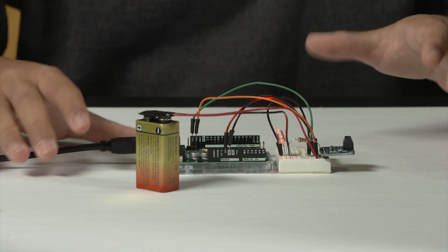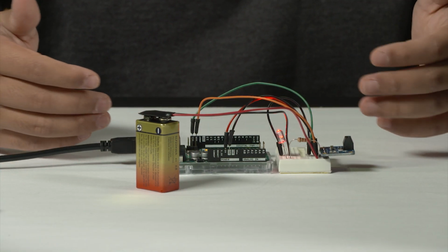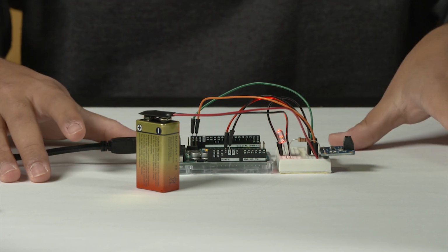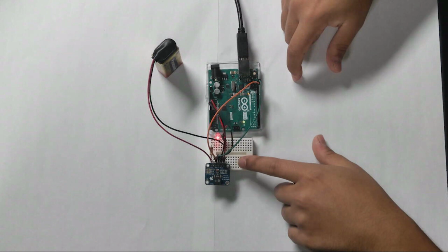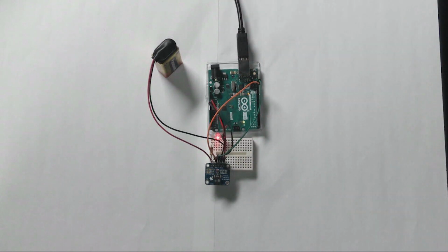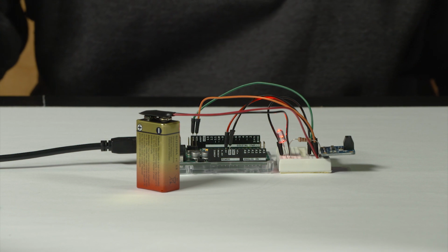Alright, so now we'll quickly demonstrate activity 2.3. Now the point of this activity is to use the circuit from activity 2.2 and actually run code on the Arduino so we can see the current readings from the current sensor. So what we're going to do is go into the Arduino library and look for the Get Current program that comes with the sensor. We're going to upload that to our board.